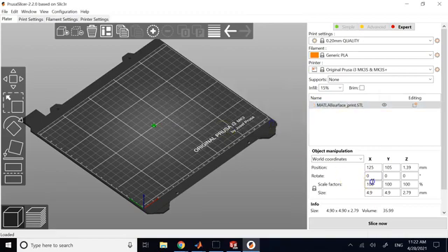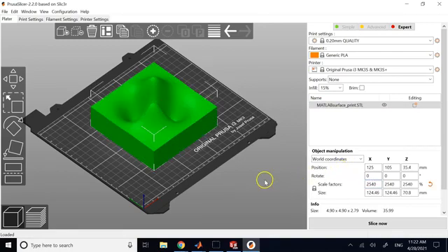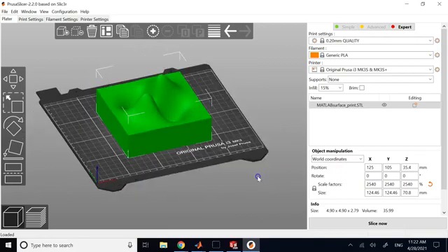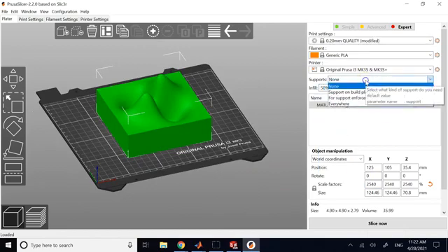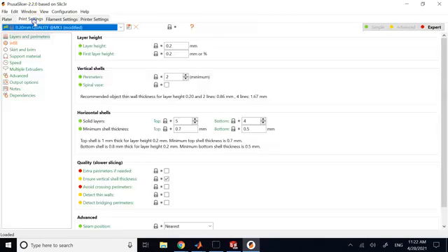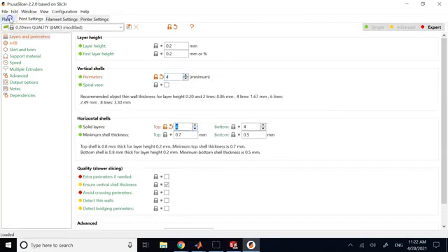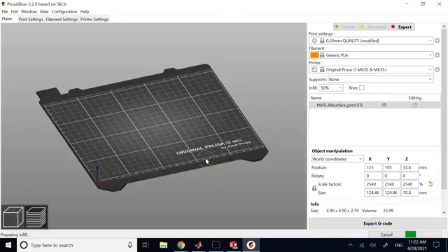And if the scale is small, I can change it. So this is in millimeters, so I can make it into inches or anything like that. Correct. And now this is good, big enough. I can give it any infill I want, and there is no support needed for this. I can give it enough shells to make it thick enough, and then what? Slice, and then it should be good to go.